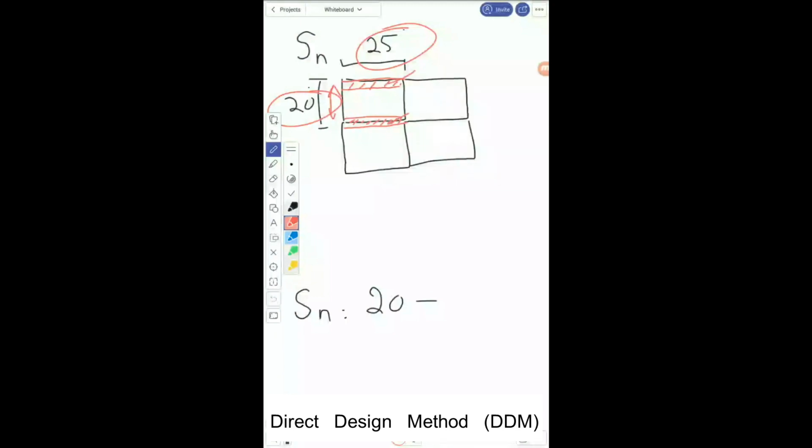See, this is the long direction, this is the long direction, this one is the short direction. These two beams, the ones I'll highlight right now for you, are running in the long direction and they have the dimensions 14 cross 28. So the width I have to consider is 7 inches from here and 7 inches from here, 14 inches.